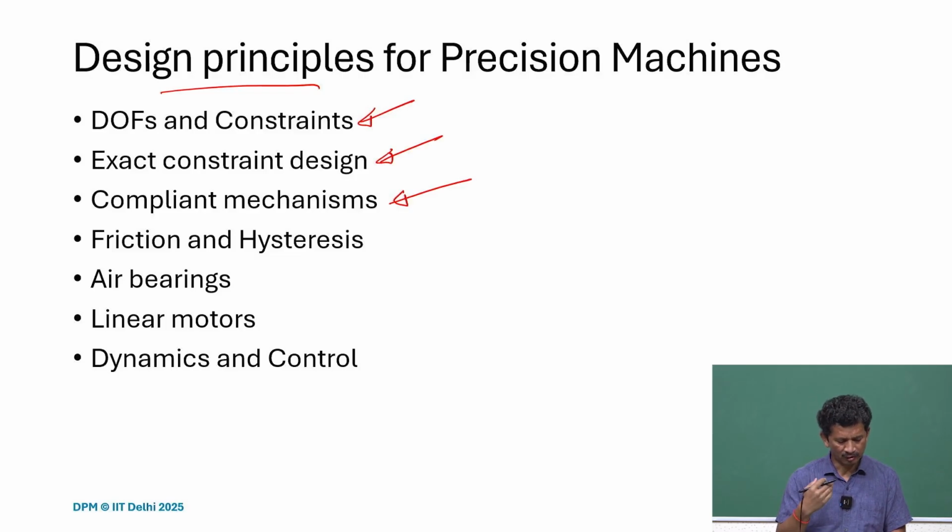So the use of compliant mechanisms, we understood. We talked about different cases, different kinds of compliant mechanisms. We also tried to address why friction is bad for precision. Yes, friction is good for damping, but for precision it's really bad. Even if there is no clearance, we still have backlash. We still have virtual play because of the friction and the limited stiffness of the system. So how to eliminate that, how to address that.